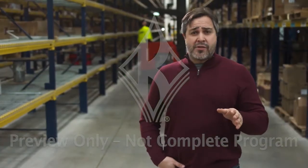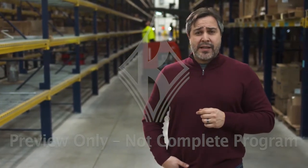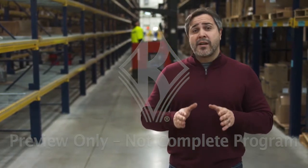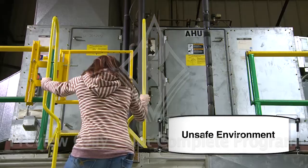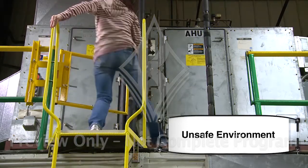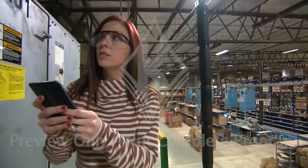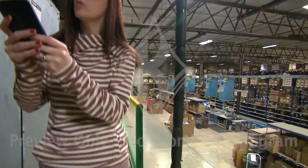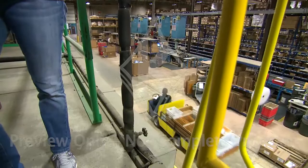In order to reduce the risk of falls, it's important you're aware of the situations that can pose potential fall hazards. There are 3 main types of hazards: unsafe environment, unsafe equipment, and unsafe behavior. Many times, it's the environment that creates the fall hazard. For example, here, the equipment is in safe working condition and the user follows protocol and exhibits safe behavior, but the environment contains a hazardous condition. There is potential for the employee to fall to a lower level due to the lack of a guardrail system or device to prevent falls.